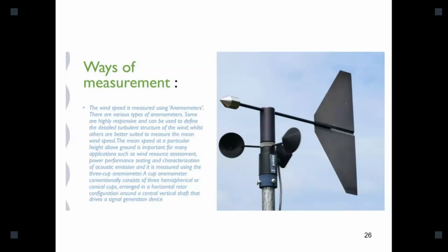Then think about where we require the quick variations. For a large wind turbine, the quick gust wind speed, do we require the gust wind speed? Yes, sometimes because of the dynamics. We may need to estimate the wind gust to find out the dynamics of the structure and everything. But for energy purposes it is not much required. For energy, the 10 minutes logging time is sufficient because the wind rotor also has a lot of moment of inertia, so that variation cannot be addressed here.